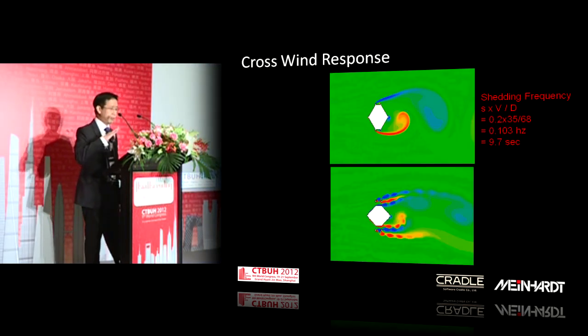Before we ran any computations, we wanted to see how the computations would do in predicting the shedding frequency. That's kind of interesting. We want to tune the structure away from the shedding frequencies to make sure we don't have a resonant response. Let's say on the upper one, we predicted about a 10-second shedding period.